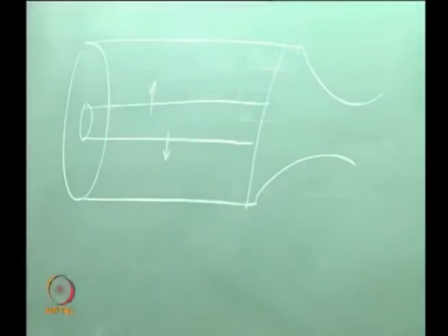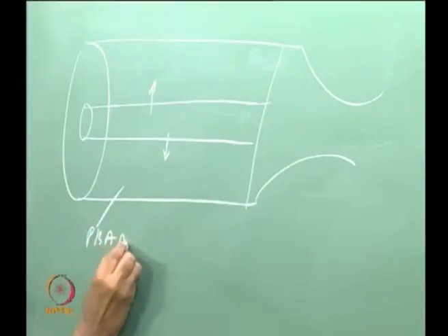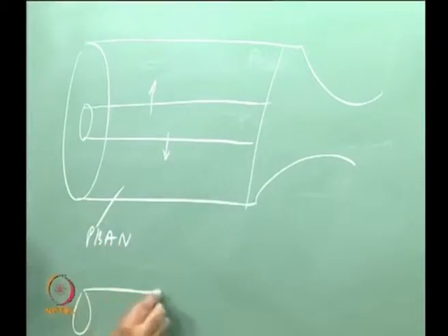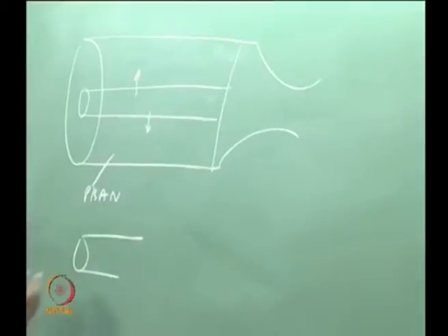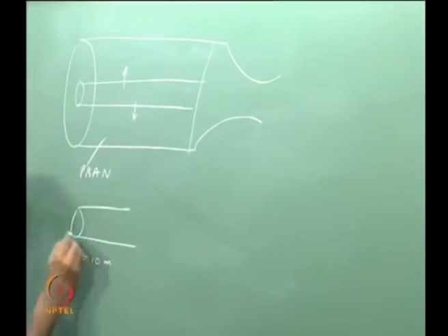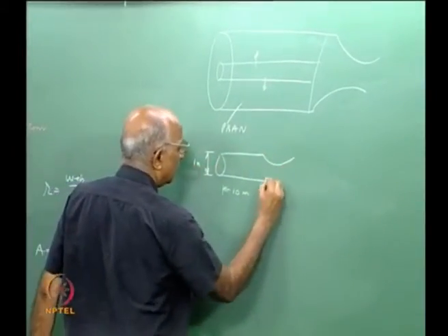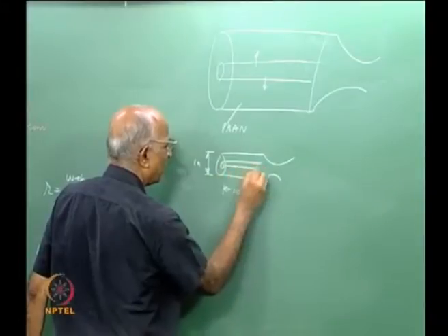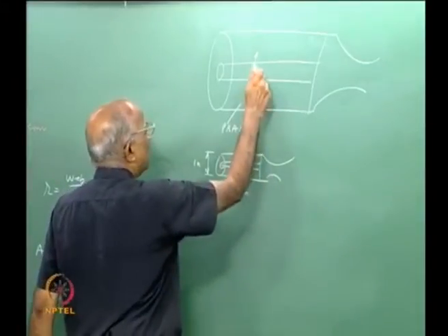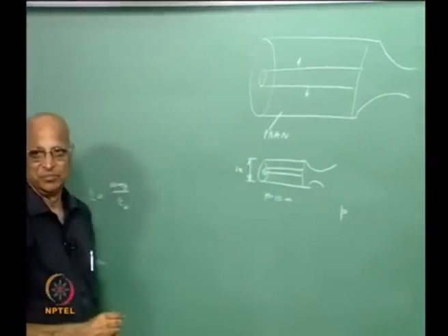Let us say I have another motor using the same P band propellant, in a small motor, not a control round, but let us say a motor 10 meters long, maybe with a diameter of 1 meter, with a similar grain. Will the burn rate in this and this, at the same pressure, be the same or different?